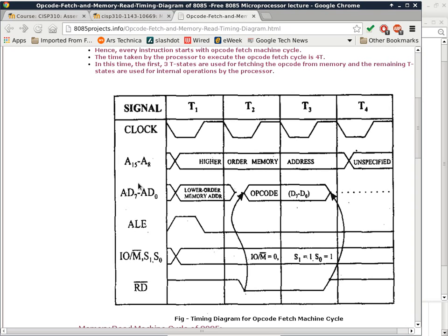So what happens is you have a layer of copper, a layer of FR4, another layer of copper, another layer of FR4, another layer of copper, and so on. So it becomes a big, huge sandwich of copper and FR4 material. So that's the cross section of a 6-layer board.